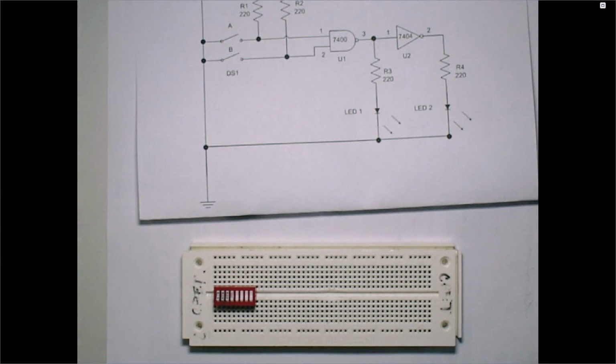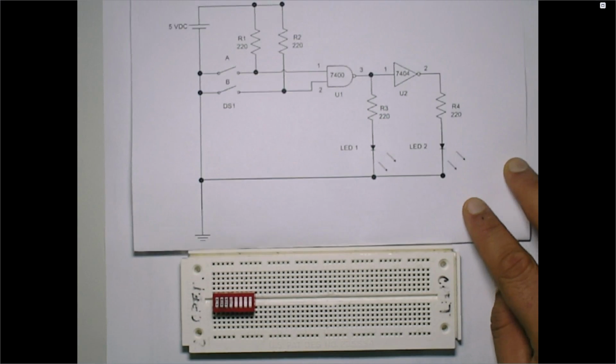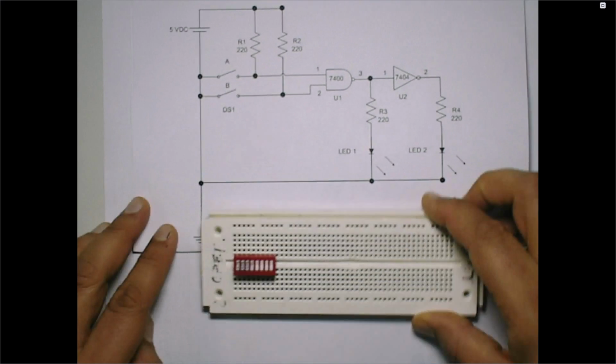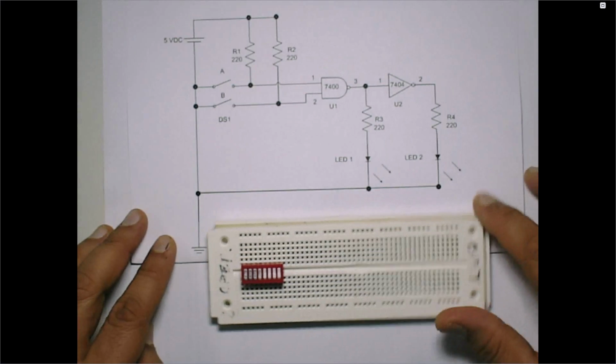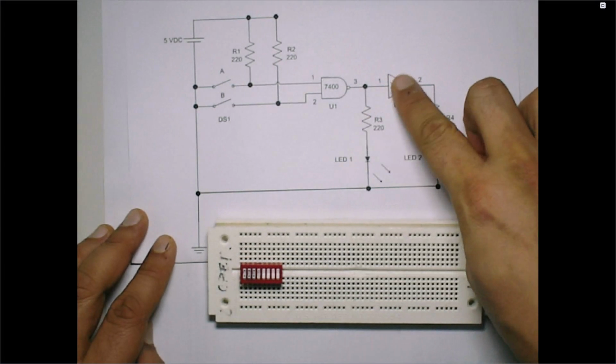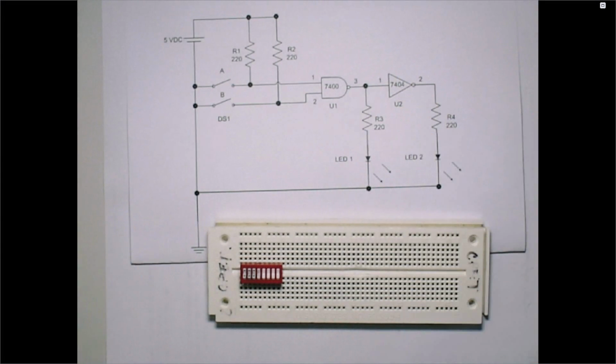Now, what other IC do I need? For this circuit, remember I was showing you the ICs that I will need. If I go back to the schematic, what gates do I have? I have NAND gate and inverter, right? I have NAND gate and inverter, so I actually need 7400 and I also need 7404, right? Now, in your package, remember I said I'll give you digital circuit parts kits, so you will see all the ICs there, okay? Now let's say these are the 2 ICs that I have, okay?